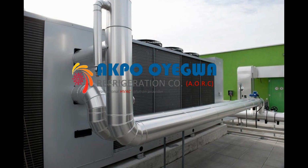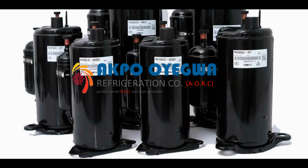6. R1234yf, HFO-1234yf. This is a new refrigerant developed to replace R134a. It is non-flammable and has zero ozone depletion potential and a low global warming potential. It's important to note that new regulations are in place to phase out some refrigerants due to their environmental impact, so it's important to check the regulations and availability in your area before choosing a refrigerant.